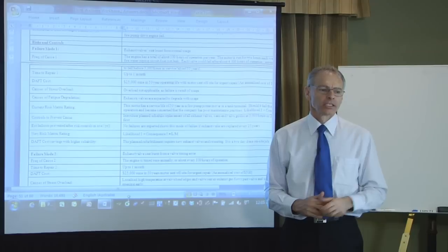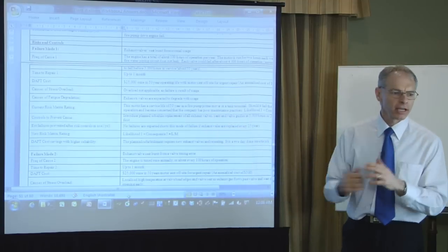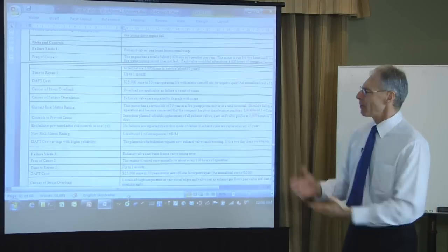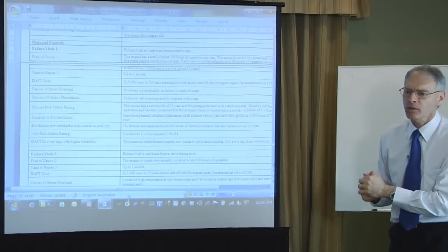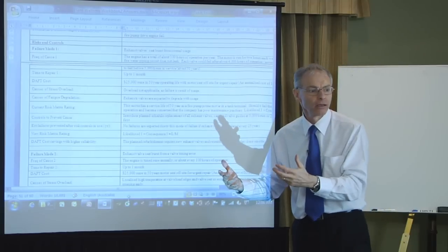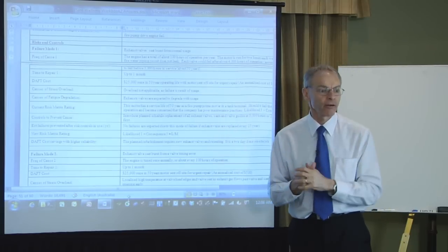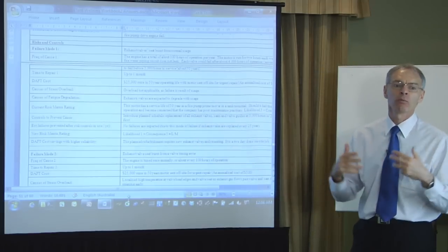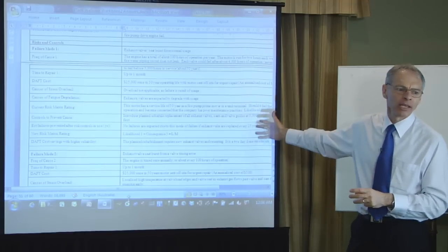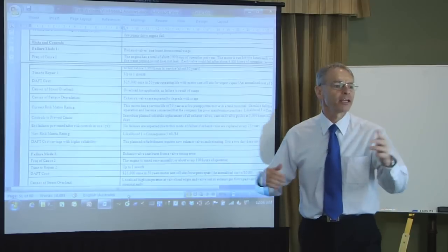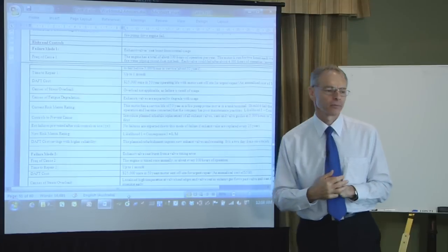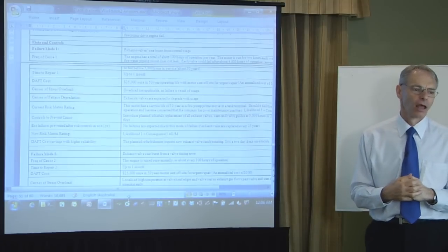Yeah. So if that is a possibility with an engine, a diesel engine, you wouldn't want to walk past that. May happen once in 100,000 engines, but that could be the 100,000th engine that it happens on. You don't know. That's what risk and chance is all about. This particular engine, you have no idea what will eventually happen. But 1 in 100,000 engines will have that very problem, and it could be this one. And is that an issue I'm willing to live with? At $500 million, no. For a $500 million risk, I'd be happy to go there every 3 years, go and redo my head gasket every 5 years under controlled conditions. Or I would tell them to get standby redundancy, get another engine.